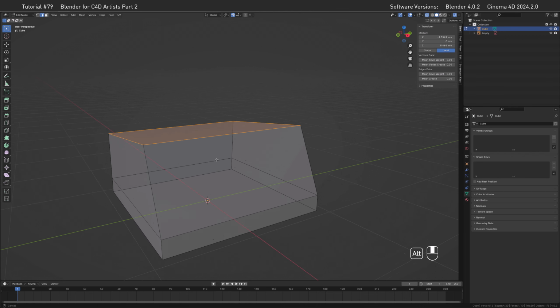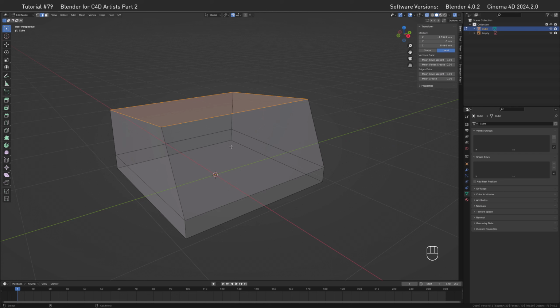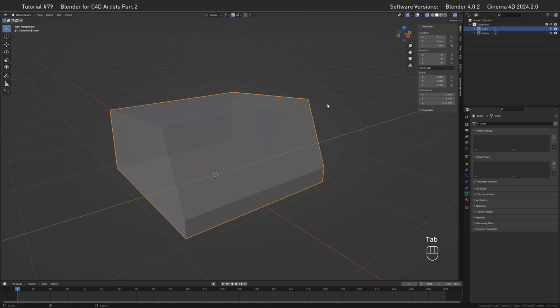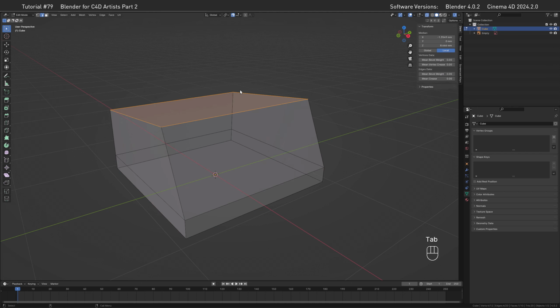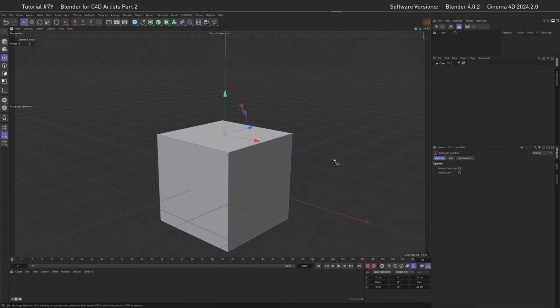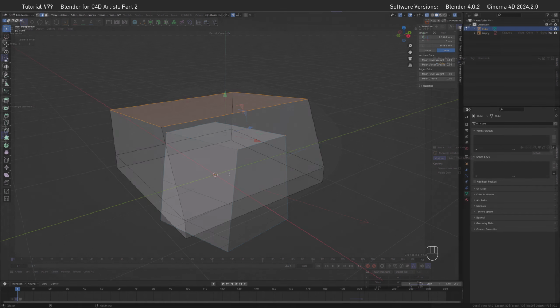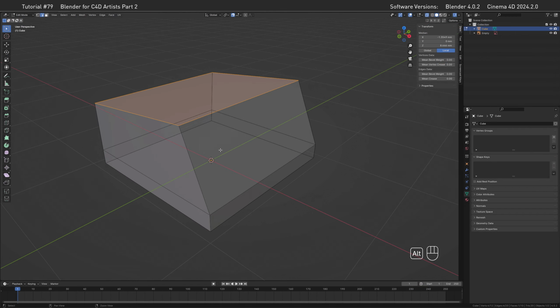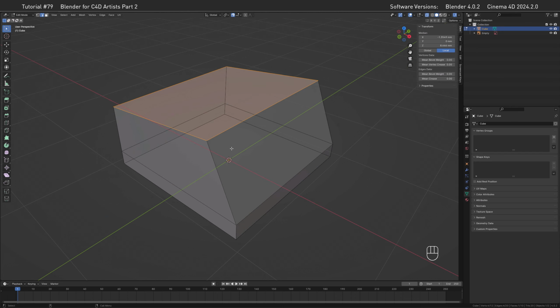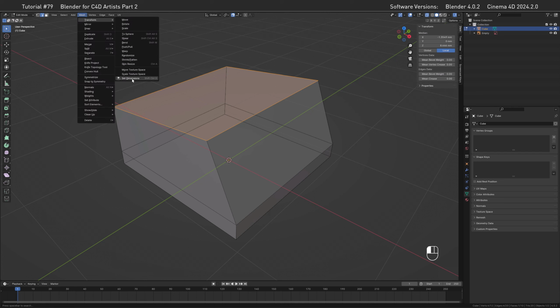A huge problem when I started out in Blender was that when I was in object mode, there's no problem in changing the size of the keycap here. But when we are in modeling mode, I'm missing this option, which is also available in Cinema 4D. After a bit of a longer search, I actually found an add-on to do this. And this comes with Blender for Artists, and it's called, or we can see it here, Mesh Transform Set Dimensions.